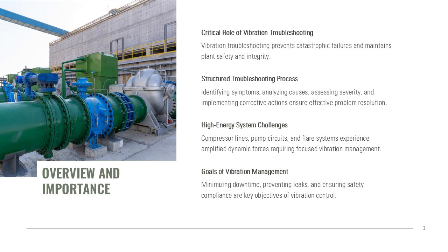By following the EI guidelines, engineers can systematically review operational history, conduct thorough inspections, perform accurate measurements, and apply both short-term and long-term solutions. The ultimate goal is to minimize downtime, prevent leaks or ruptures, and maintain compliance with safety standards. Understanding the signs of vibration, such as fatigue cracks, fretting, and audible noise, is the first step toward effective troubleshooting. This introduction sets the stage for a detailed exploration of identification techniques, diagnostic steps, and mitigation strategies that form the backbone of vibration management in industrial facilities.